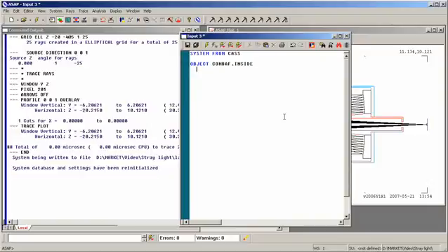I'm going to assume that the scatter property is Lambertian, that is to say, the scatter characteristics, or BRDF, bidirectional reflectance distribution function, is constant as a function of incident and scatter angle. The easiest way to do that in ASAP is to enter the scatter command. Scatter random. I enter the diffuse reflectance, which for a diffuse black surface is typically around 5%, or 0.05, and